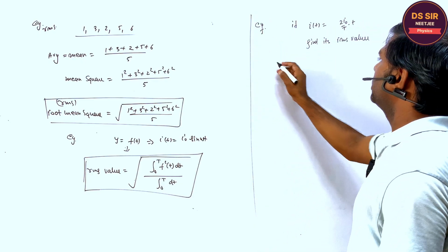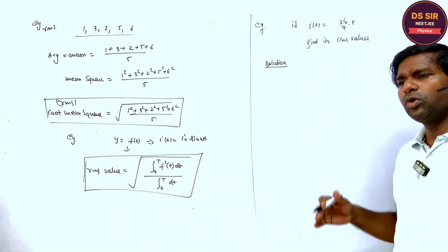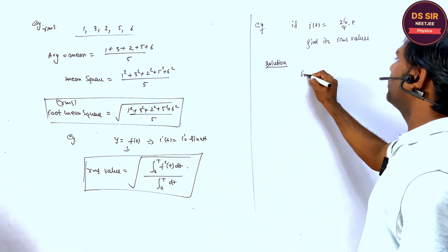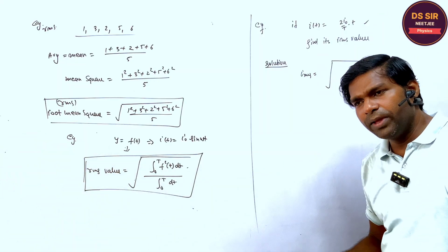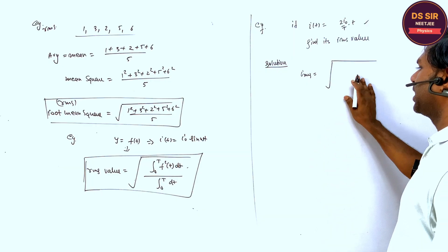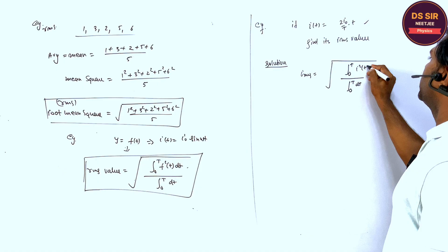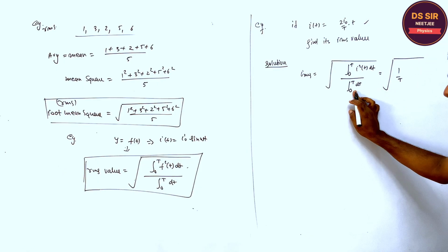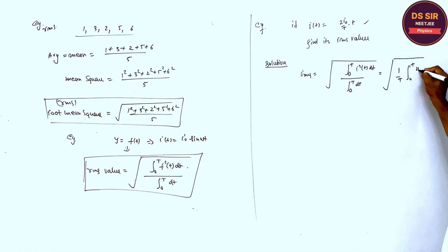Listen one thing. To find the RMS value, whether it is a sinusoidal function or some other periodic function, we will use this formula. So the IRMS value is nothing but the square root of the mean square value, generally found for the capital time T. So from 0 to T of I square t dt. It may be written as this integration. You understand this? And from 0 to T, what is it? It is 2I0 by T whole square into t square dt.